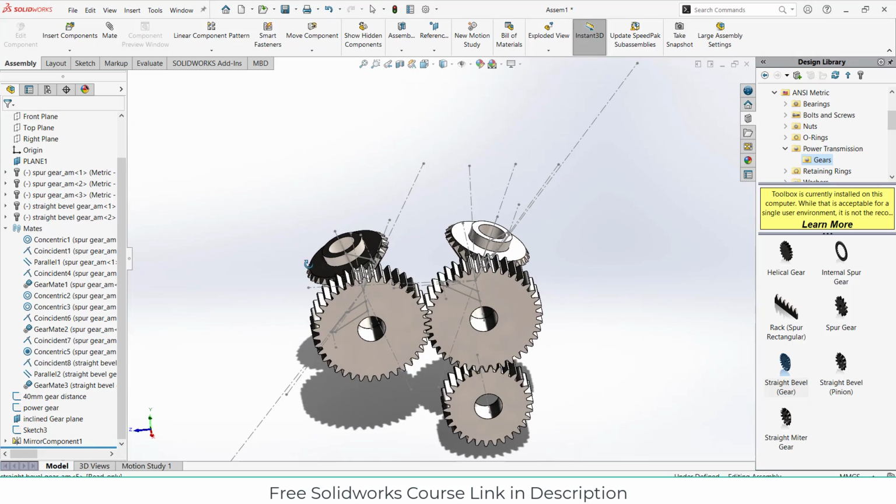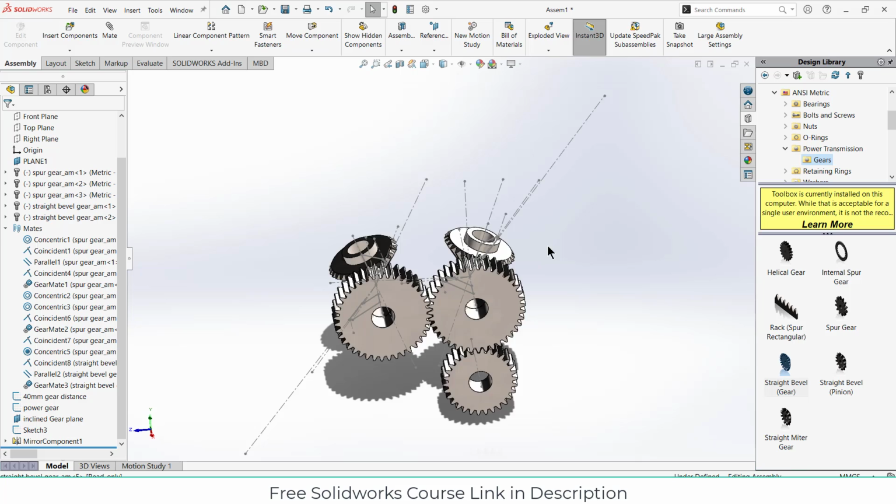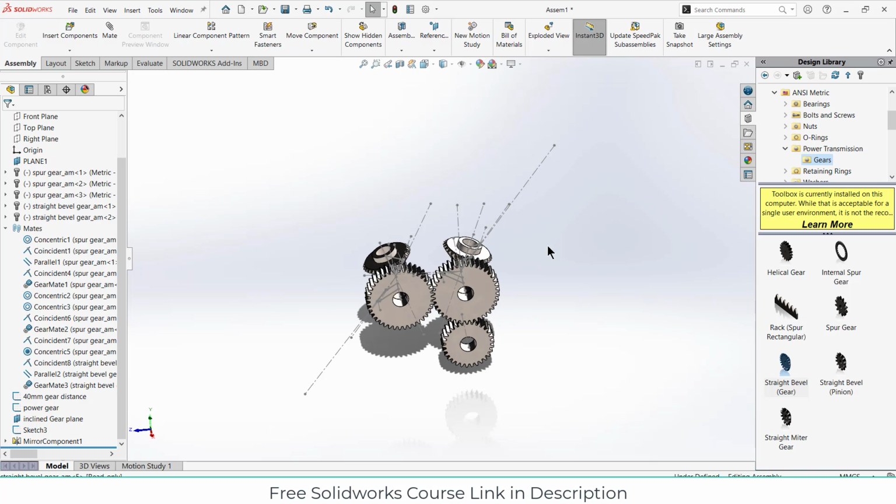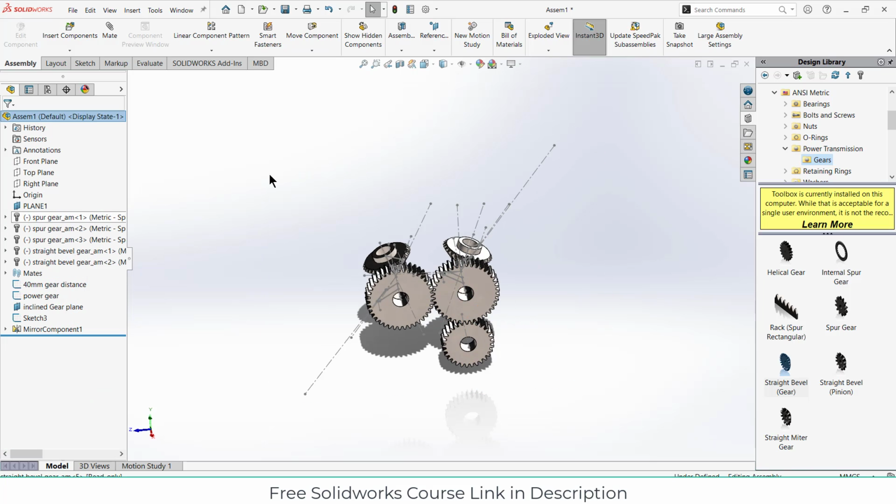Now, the other thing that I have to create is the fan blades. After that, we will work on the base part. So to create fan blades, I will not do any kind of hard work. What I will do, I will simply create a shaft and create a blade on there. First, let's remove these annoying sketches.